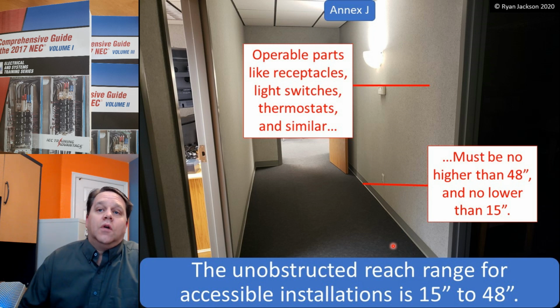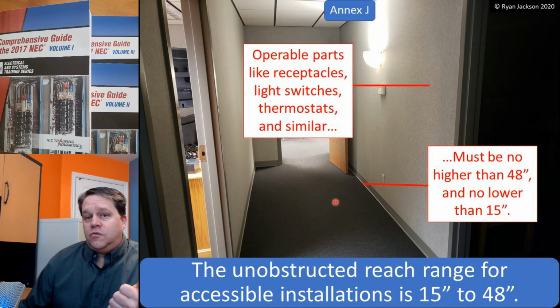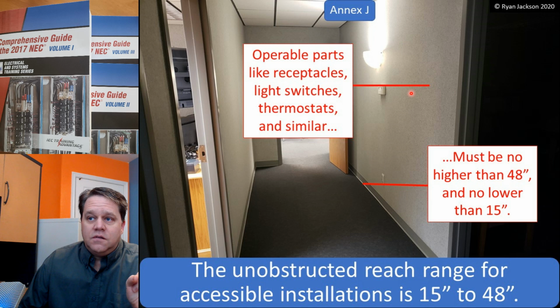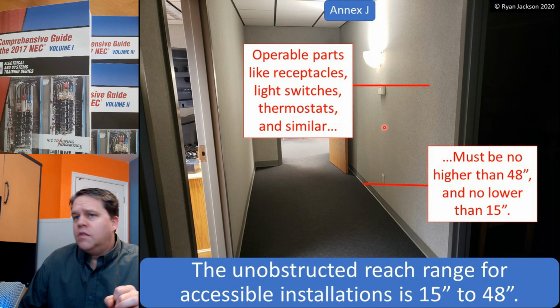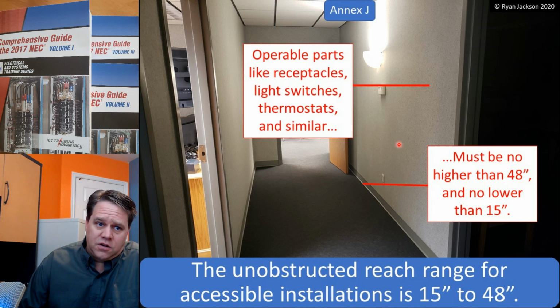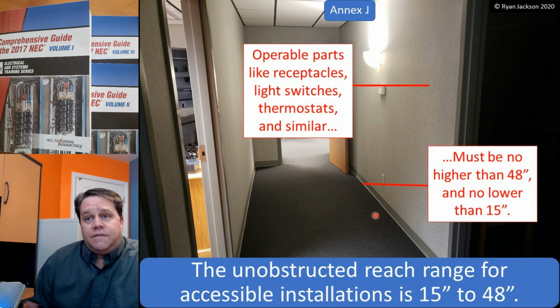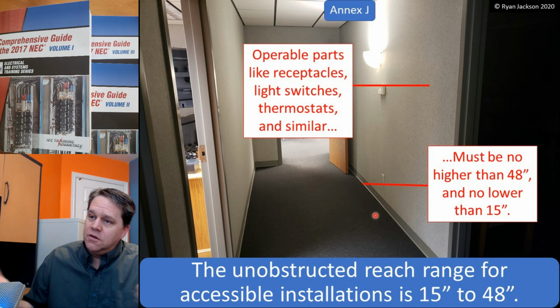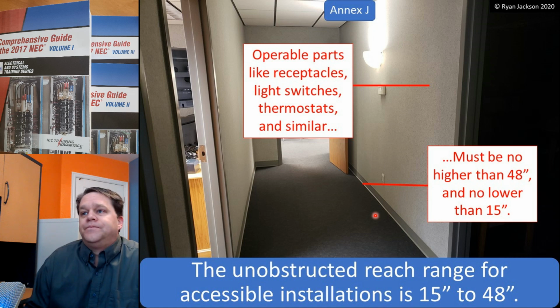Employee work areas do not. So inside this guy's office, we're okay. In this corridor, well, we've got regulations. Operable parts like light switches, thermostats, receptacles, they must not be any higher than 48 and no lower than 15. Thermostats is a very common violation. The typical height that I see is 5 feet. If you want to put it 5 feet in your own office, be my guest. If you want to put it 5 feet in a hallway, no can do. It's got to be accessible.